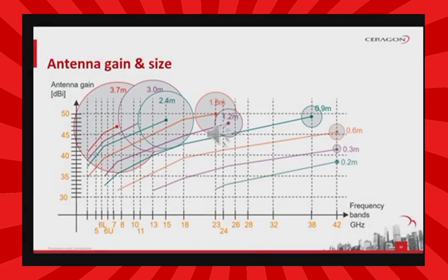This diagram, which has antenna gain vertically and frequency band horizontally, will give frequency ranges, approximate antenna gain and relative antenna size. The diagram verifies that radio link antennas have a gain between 30 to 50 dBi and that lower frequencies demand a larger antenna diameter. Please note that the diagram is not accurate enough for link budget calculations. Precise antenna gain figures can be found in data sheets.